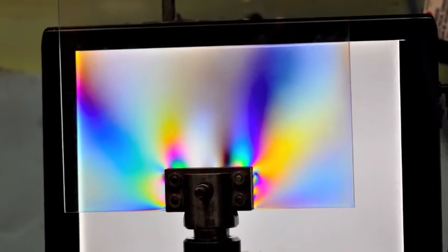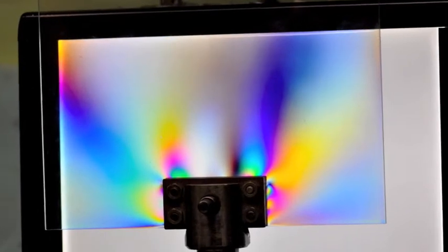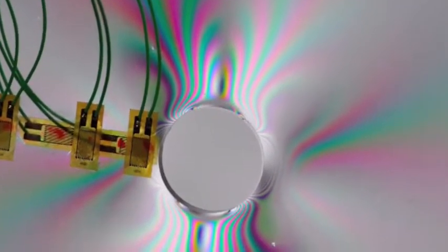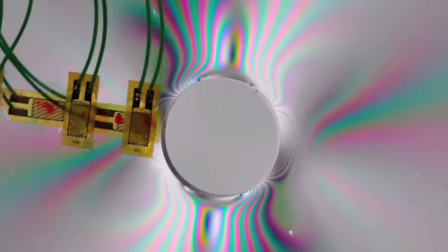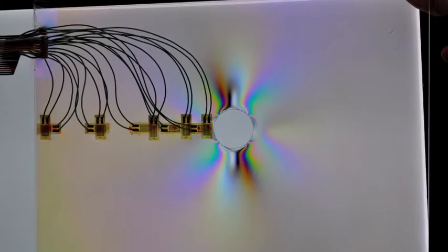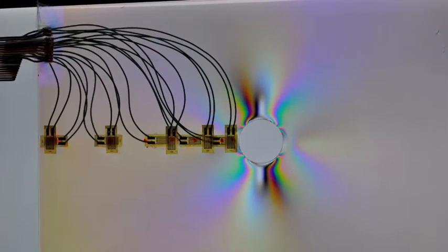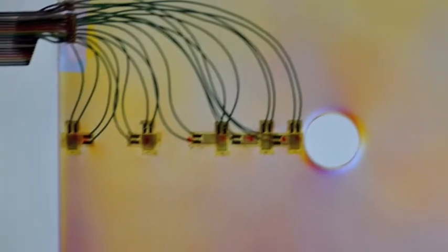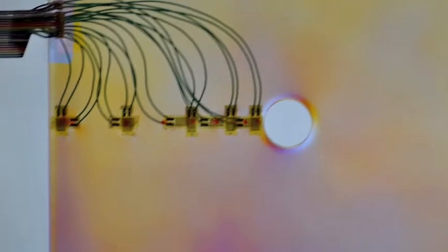The pictures do an even better job showing the areas of stress concentrations. At the clamps, there is a high level of stress around the points of contact. However, this report deals primarily with the area directly around the hole. At the hole, there are high levels of stress in the Y direction and relatively small in the X. The devices lined up along the HH line of the plate are extensometers, oriented either horizontally or vertically. These devices give data that provide the means to calculate the plane stress in the X and Y directions.